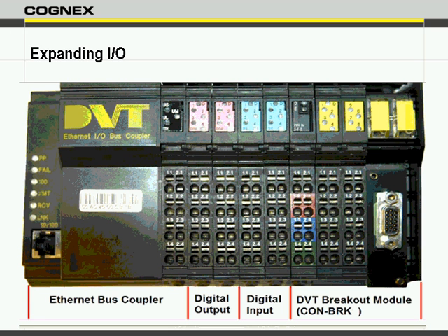And not only that, we can start ganging these, so it's not just 8 more outputs. We could have 16 outputs and 8 inputs, however you want to configure those. So this allows you more hard contact points for your camera through the Ethernet I/O. And where you will find that function is right here in the communications again. We'll go back here to digital I/O, and this is our Ethernet I/O. We've discussed virtual, started with physical, and here's the Ethernet I/O. Let's open this up.